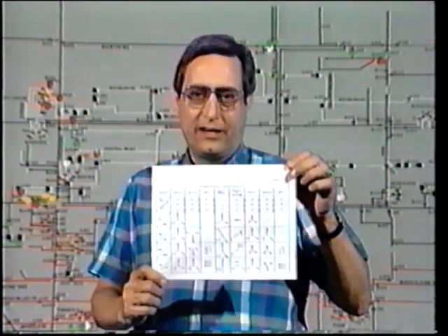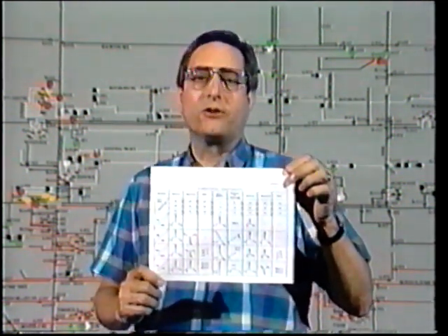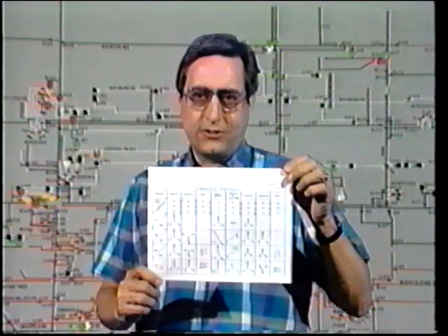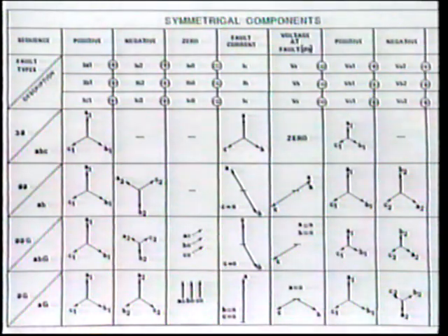Included in your workbook is a table of standard diagrams showing symmetrical voltage and current phasors for different fault conditions. Take time to study this and take particular note of the relative magnitude of phasors for different fault conditions. In performing fault analysis for unbalanced fault conditions, the major task is in calculating the values of symmetrical components in terms of both magnitude and phase angle. We're also faced with the problem of adding together quantities that are acting at different phase angles relative to each other.